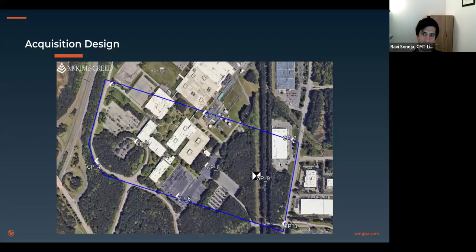A good analogy is trying to pin the data set down like a sheet of paper to a table, so that if wind came from one side, it wouldn't lift on that side. But the control itself was set using base rover methodology. The base station coordinates themselves were derived through a 45-minute occupation. 2 days after that occupation, that data was submitted to OPUS to derive the coordinates.